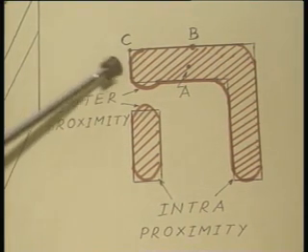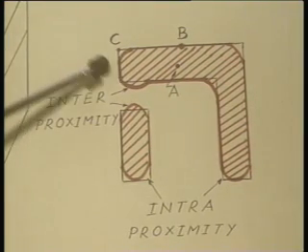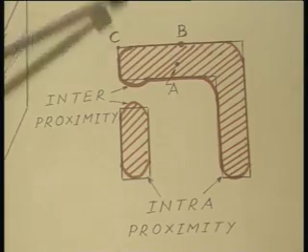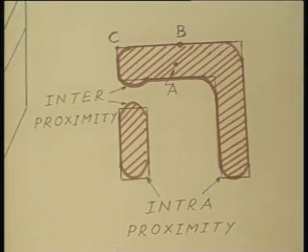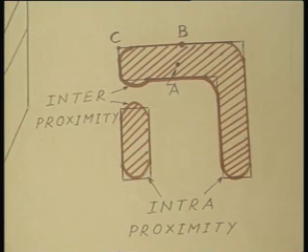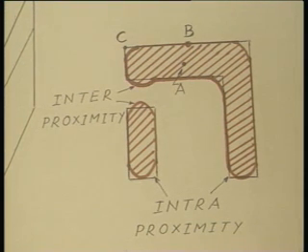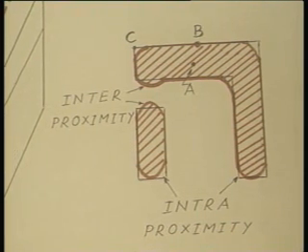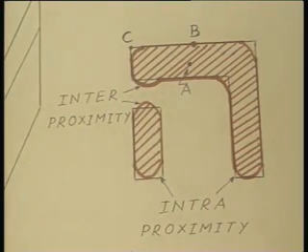Point C is of course at a still more disadvantageous position. Point C is at one corner and therefore, compared to point A, it is receiving only 1/4 of the total E-beam radiation. Therefore, you see the amount of E-beam radiation received by different points on a pattern is not the same.